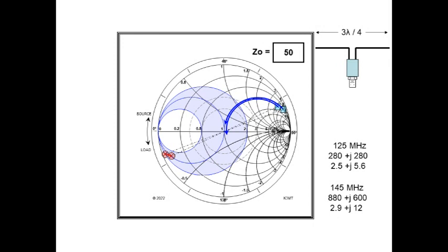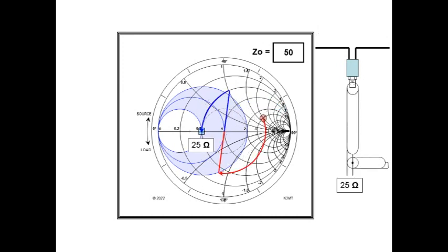Suppose the first length is shortened, and just reaches the shaded border. Then the final impedance can be brought to 25 ohms, not 50. The right length, which just reaches the center of the shading, renders final impedance to 50 ohms. A longer piece renders it to 100 ohms.